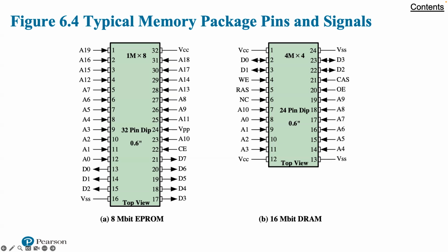A chip enable CE pin: because there is more than one memory chip, each of which is connected to the address lines, the CE pin is used to indicate whether or not the address is valid for this chip. The CE pin is activated by logic connected to the higher order bits of the address lines, for example the address bits above A19. The use of the signal is illustrated presently, so keep that in mind. We'll show some block diagrams. There is also a program voltage VPP that is supplied during programming write operations.